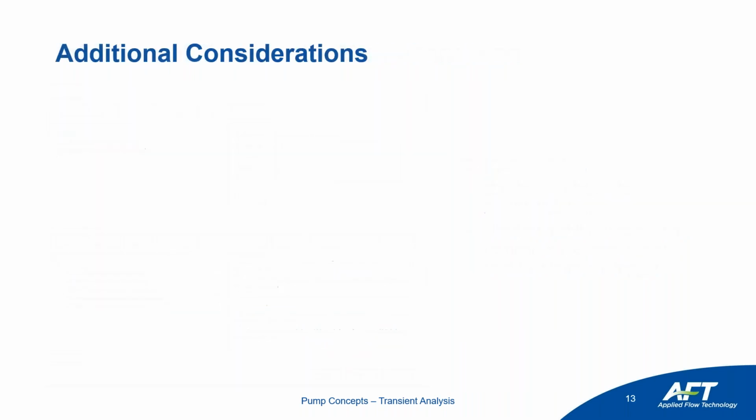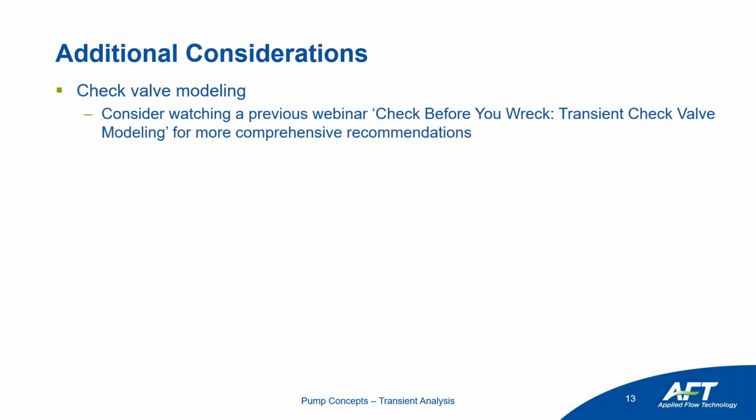Some additional considerations. Check valve modeling. So how much check valve slam occurs depends on how you're modeling that check valve. I would consider watching a previous webinar I did this year called Check Before You Wreck: Transient Check Valve Modeling. That'll be much more comprehensive in terms of what to consider. Again, much more tangential to the pump transient, but it is an additional consideration that you should be looking at as you're looking at pump trip events.